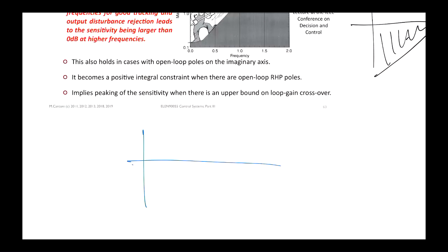The complementary sensitivity function will be something like this, and if it's popping up, which it'll always do if the output sensitivity function pops up, you might be pushing the crossover frequency to the right to make things faster, but then this starts happening. And as you keep pushing it further to the right, it keeps on peaking up.